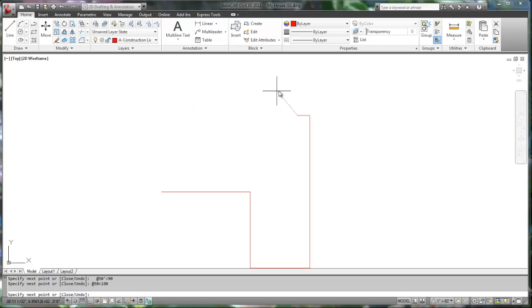That line is obviously too short. I forgot the foot symbol. AutoCAD has assumed inches. Notice in the running command that there is an undo option, which steps back one segment. Type the letter U and press enter. Now re-enter the undone line, 50 feet at an angle of 180 degrees, remembering to include the foot symbol.